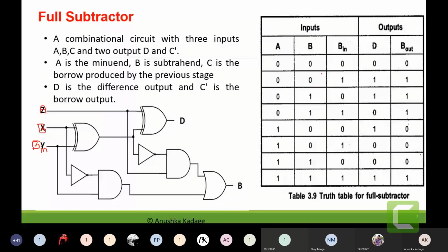If you write the truth table K map accordingly and specify the ones corresponding to the min term representation, the K map solution will give the implementation of the gates like this for the D variable. And similarly for the B out also, with these three input variable combinations, but the output taken from this column, the other K map we have to specify.